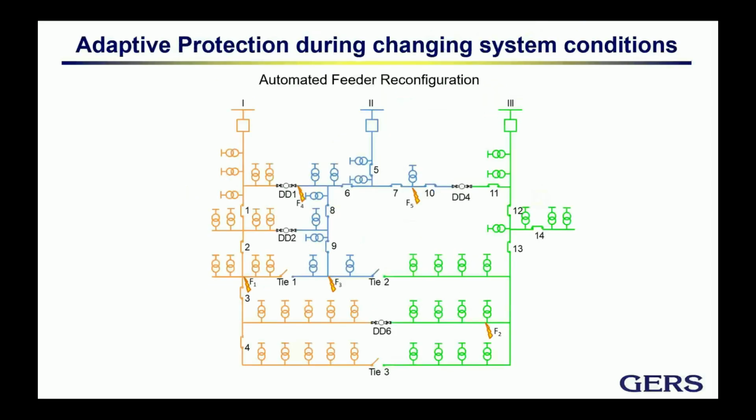Okay, another good and simple example. I will only cover 1 or 2 cases. I have here a more clear presentation. Here we have also 3 feeders. We have here the digit 1 that indicates double dead ends, I mean, where we don't have any switch. Remember that the location of switches is quite important. So to connect feeders 1 and 2, let's say we had 3 options. Eventually we picked the 3rd location. So instead of having here a double dead end, we installed a switch, okay?